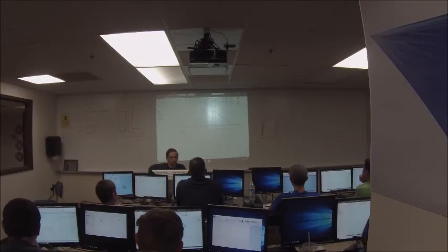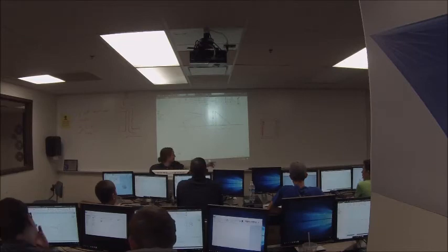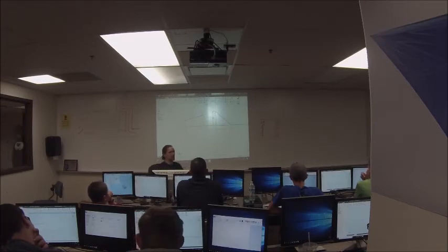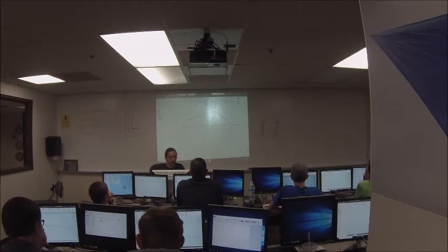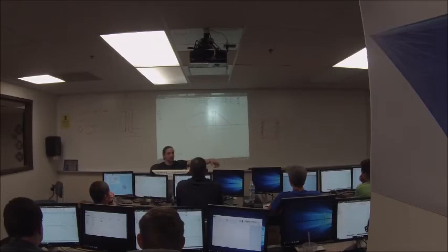So going back to what I was talking about before, where you've got two lines, I can just click and drag one line, snap it to the other. You'll notice you get that little green dot. That little green dot is telling you it's going to automatically place a coincident constraint there. So now these two lines are attached. So coincident constraints can often be placed just by clicking and dragging and snapping one thing to another thing, right?